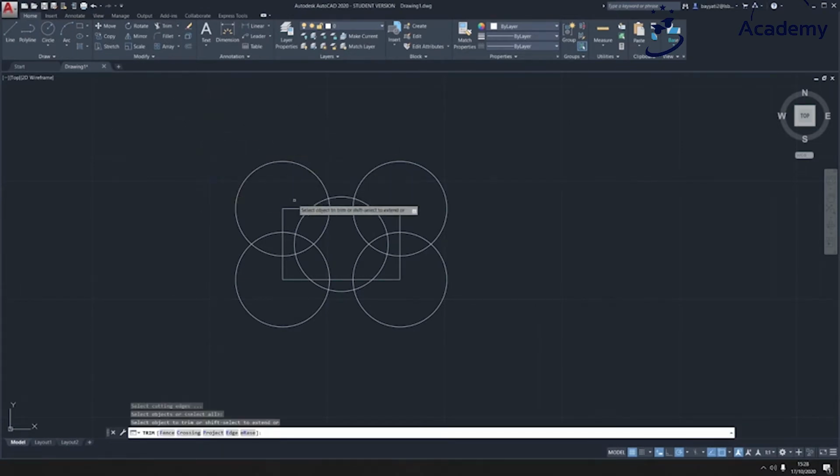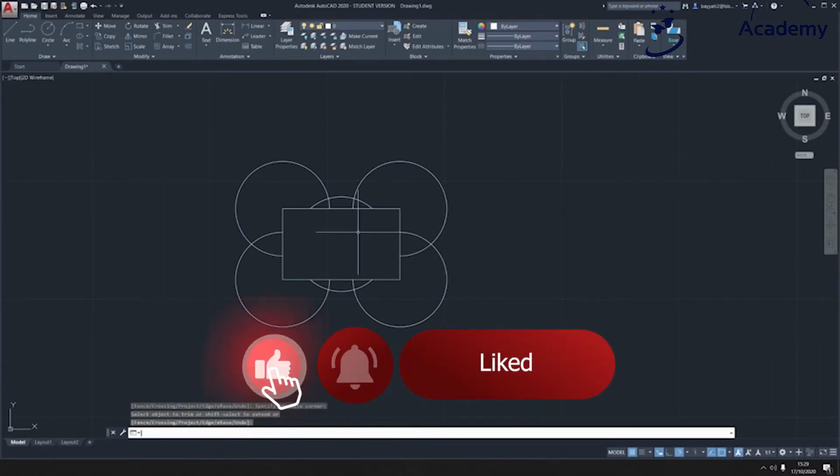And then if I put my mouse over certain areas, you see it shows what they would look like if a part was removed. So if I click inside the rectangle, and click on all the different parts, you see I can trim away the parts of the circle where they contact the rectangle. Okay, and when I'm done, I can just press enter.